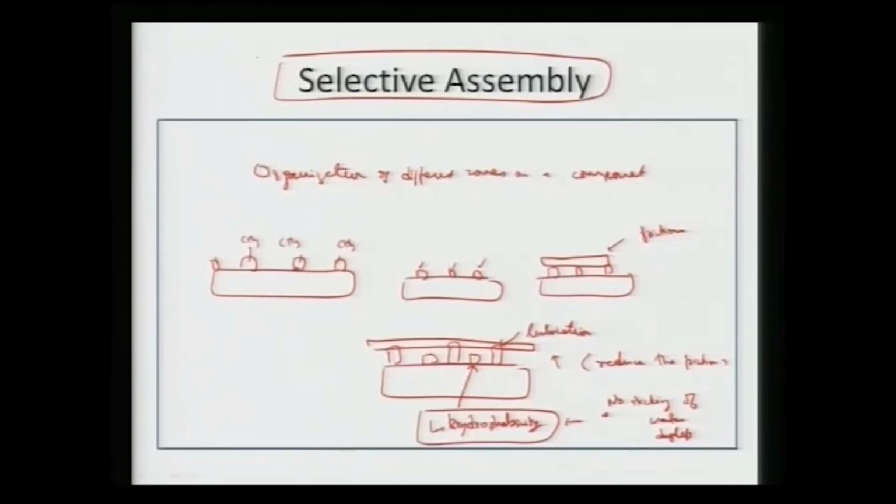A particular component has to be utilized in a wear condition where we have even water. So, we want to impart lubrication to it by polymerizing a particular polymeric chain or functional chain, and then we can also impart non-wetting to the surface by applying a layer. In that case we are able to achieve lower friction as well as hydrophobicity or super hydrophobicity on the same component. That is nothing but the selective assembly. By utilizing that we can achieve dual functionality.